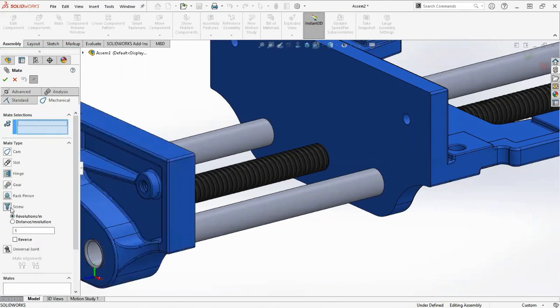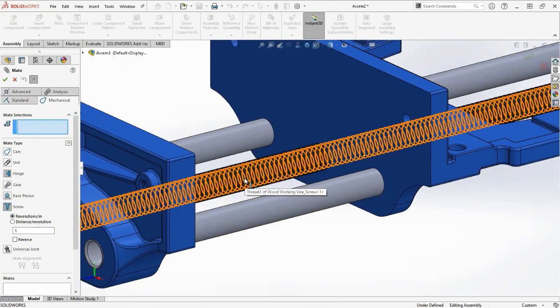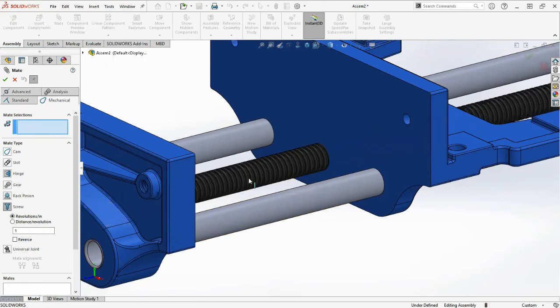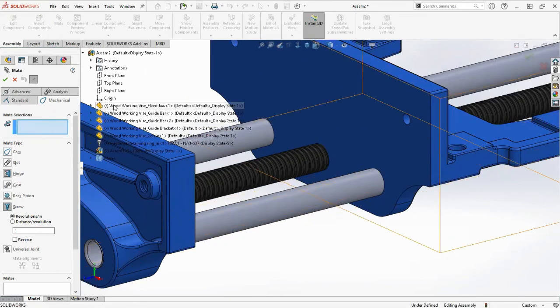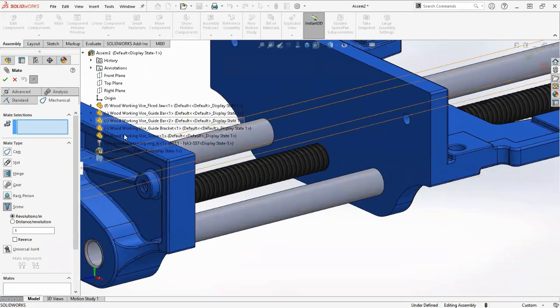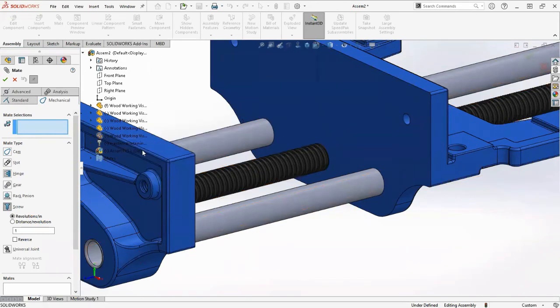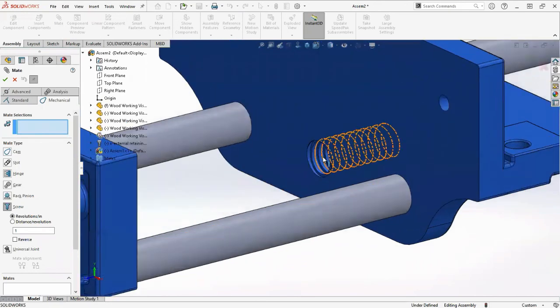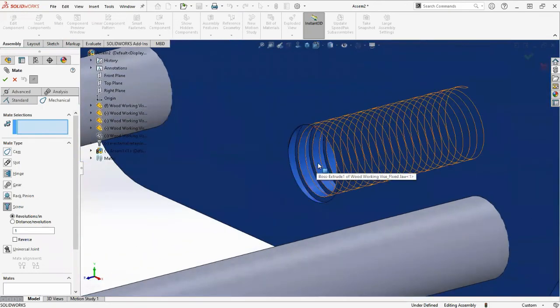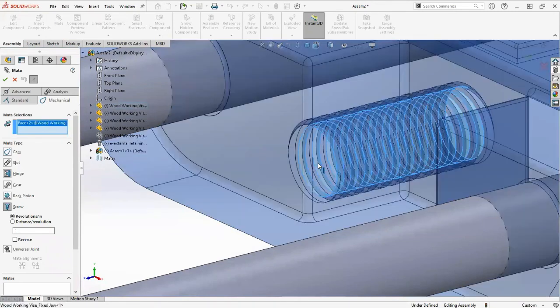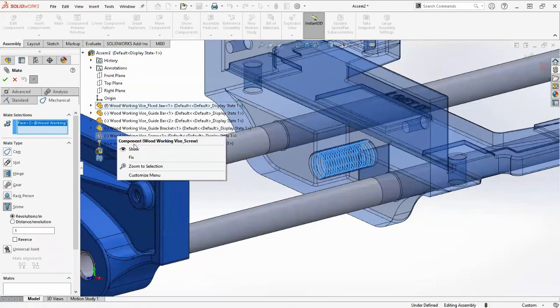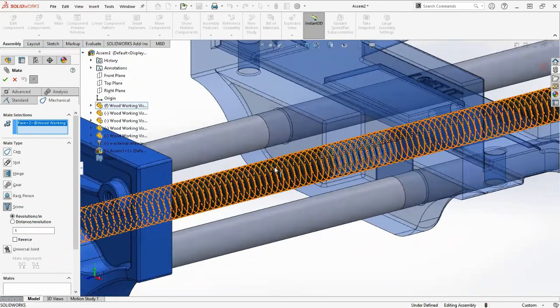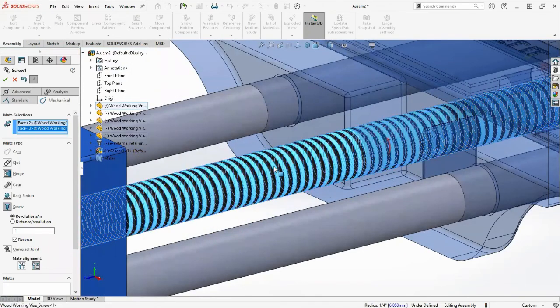We're going to define the screw mate using revolutions per inch. We'll start off with 1 revolution per inch. And I'm just going to hover this and hit tab. Guess it won't let me do that within the active command, so I can do my feature flyout and right click and choose hide. So now I can see the geometry in here I want to select. I'm just going to select this cylindrical face. I'll go back and show the screw and select a cylindrical face for it.